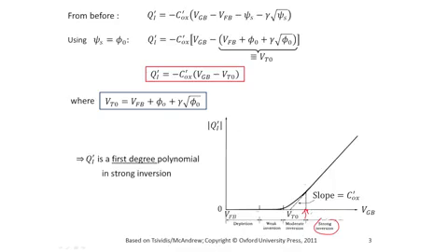In other words, the equation here is valid from this point on, but in the equation there is a parameter VT0 which is outside strong inversion. Now, don't make the mistake to assume that as soon as VGB is above the threshold, you're in strong inversion. You are not. You need a couple of tenths of a volt before you get to strong inversion. We'll talk more about this later on.